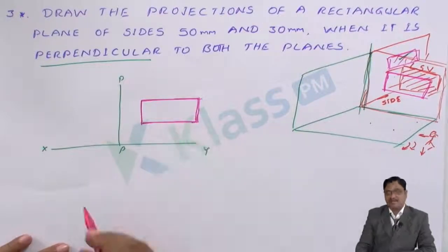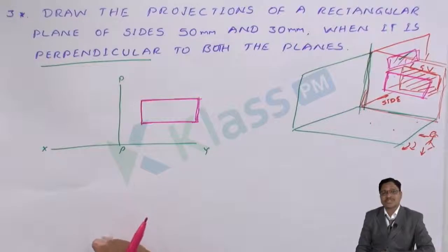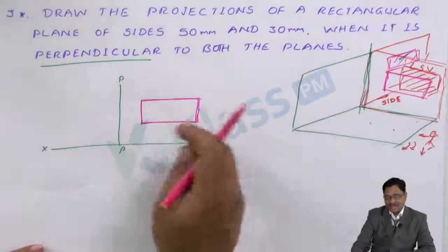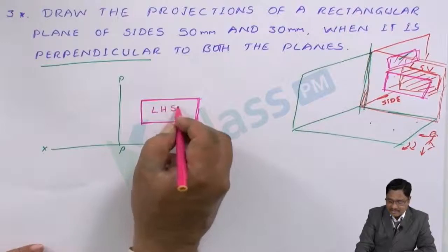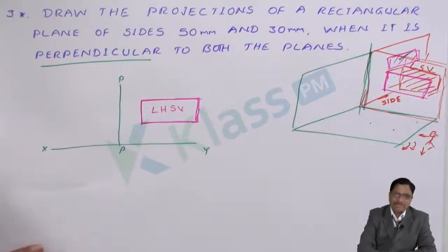As we said earlier, at the beginning of the unit, we discussed all the fundamentals. In first angle projection, the view position will be interchanged compared to the direction of view. I am viewing from the left, but my position is on the right side, yet it gives the left-hand side view. So from this you have to generate the other views. How can the other views be generated?